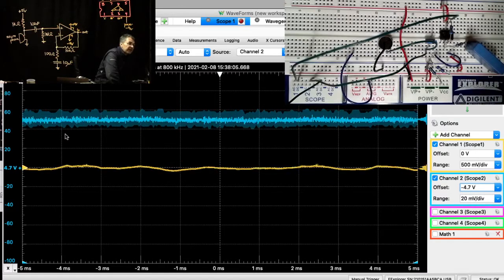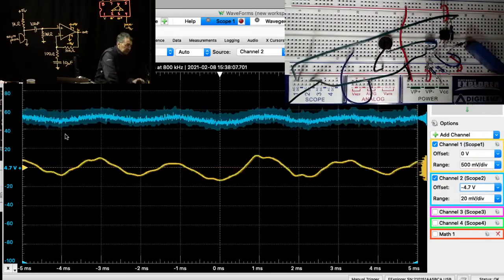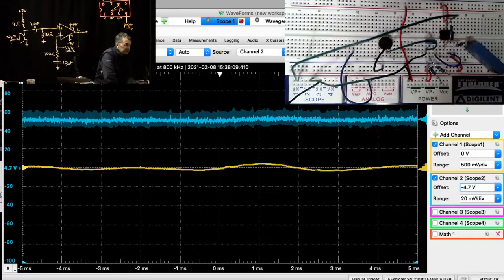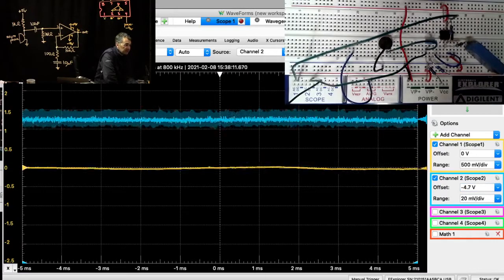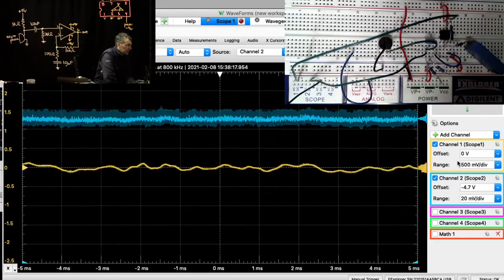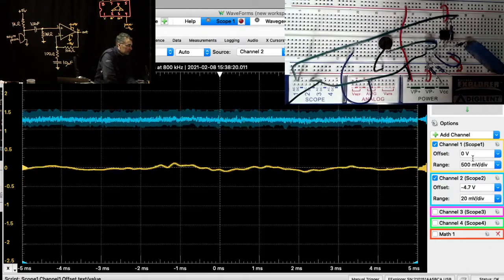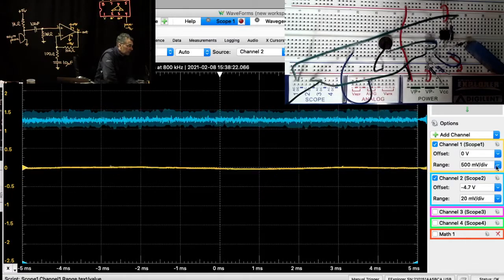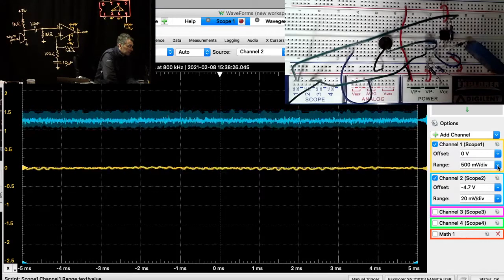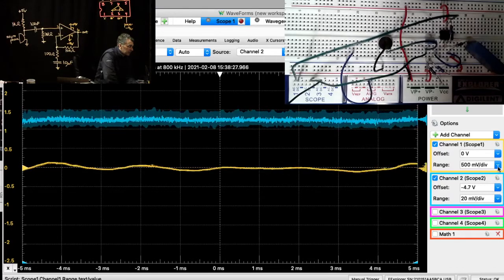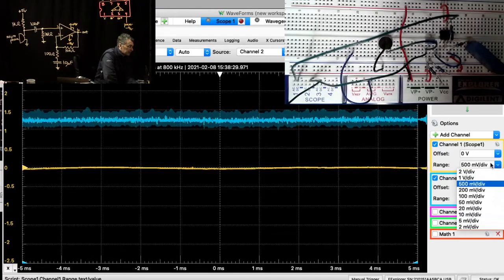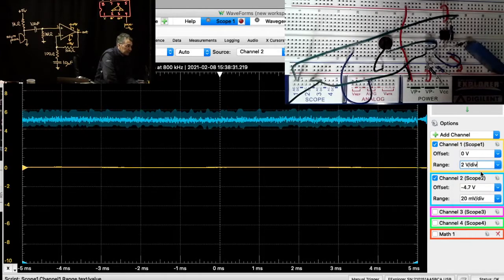I guess we also wanted to ask ourselves what happens when we tinker with the circuit. One thing we wanted to ask is what happens when we remove that 1 megaohm resistor. I claim that we will go to either plus or minus 9 volts on the output of the op-amp.